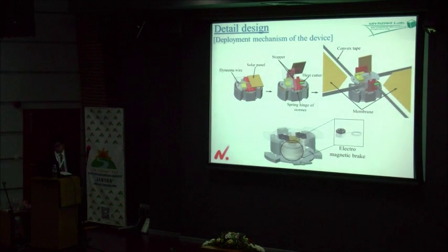The sequence of the deployment is illustrated in this video. The detail is as follows. The convex tape wrapped around the hub, the membrane are folding in case. The deployment mechanism including membrane and tapes are pushed by two stopper under the solar panel. Both stopper are held down by dynamo wire. The proposed device has conventional port release mechanism using wire and heat cut system.